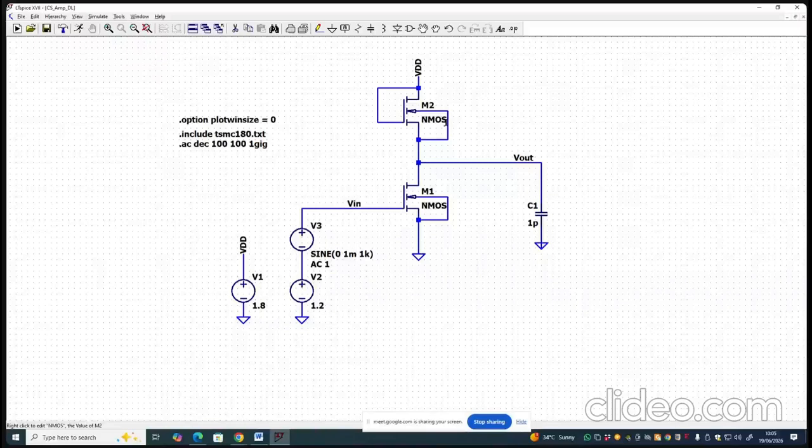Like this. But if you remember yesterday, I told you that the body of N MOSFET is connected to the most negative voltage available in the circuit, and body of P MOSFET is connected to the most positive voltage in the circuit. Okay, let's go ahead with this connection, which is not altogether wrong, but it poses a challenge in doing the layout. But the advantage of this connection is that the threshold voltage does not vary with the voltage swing at the output, because VSB is 0. So body bias effect will not be there.